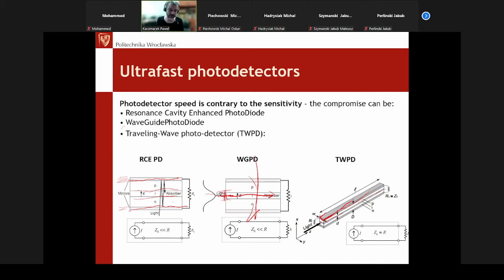And these microwave detectors, of course, are designed for a certain bandwidth. They typically aren't able to operate from, let's say, 0 hertz up to the maximum value, but are designed, for example, for from 10 gigahertz up to 20 gigahertz of operation or something like that.